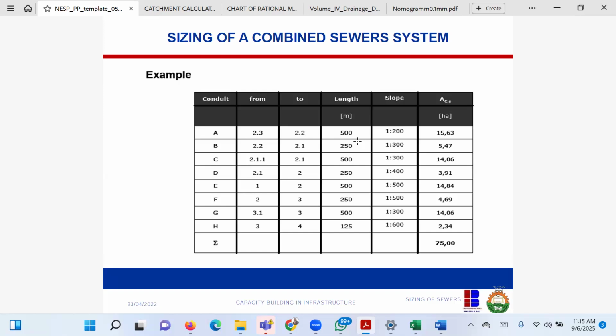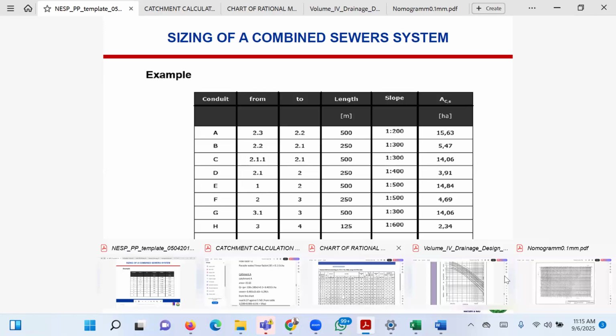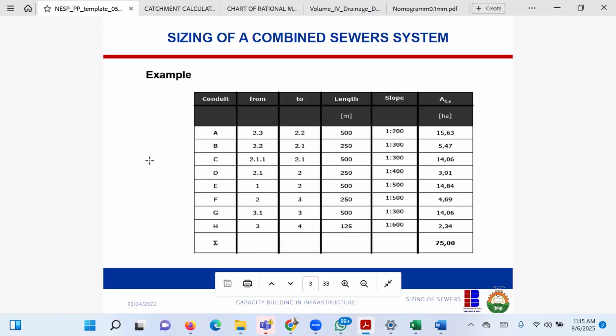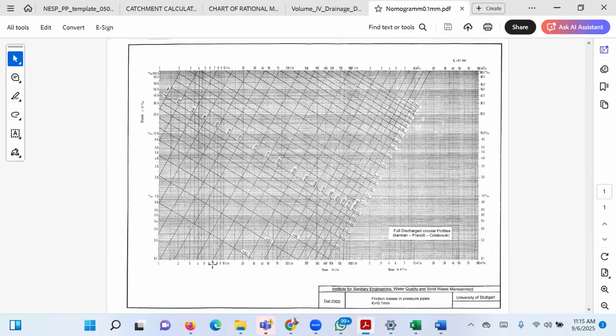Okay, so it means, hold on, 1 divide 200. So the slope is 0.005. Then, if I now want to use my chart, what does my chart say? My chart says I have to multiply it. If I do it per 1,000, it means multiply by 1,000. That will give me 5 per 1,000. So when I come to my chart, I'm going to read this value against 5.